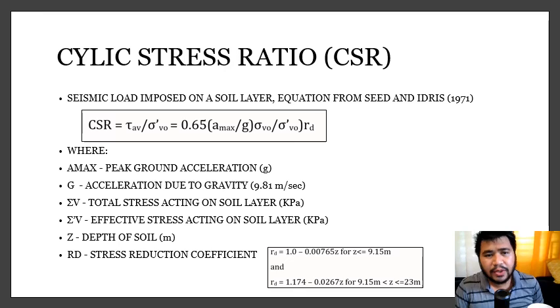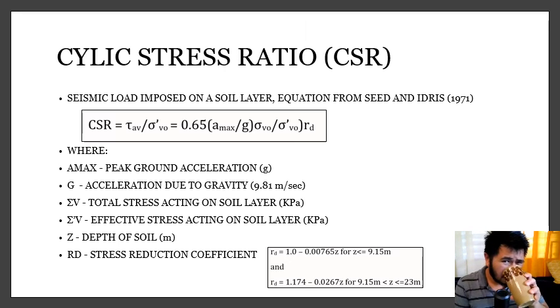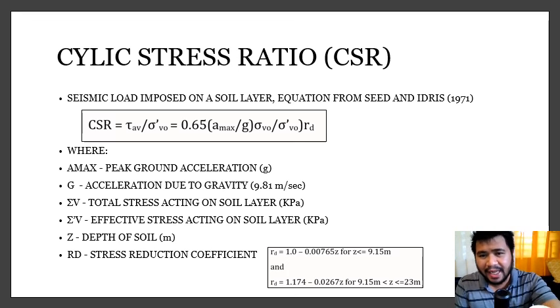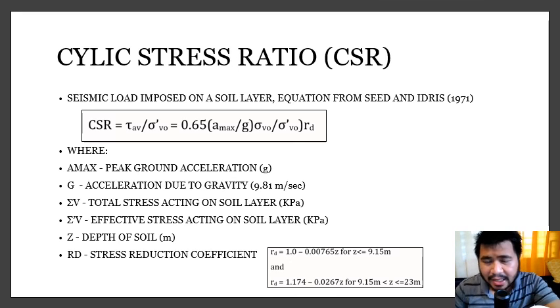Cyclic stress ratio is basically the load that is being imposed on your soil layer during the earthquake. The equation is based on Seed and Idriss, 1971.